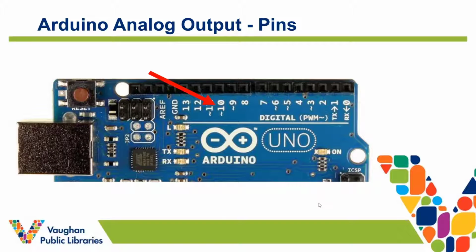If you remember Arduino Uno, we talked about that before, it has a couple of pins on the top side and a couple of pins on the bottom side. For example, analog input pins are on the bottom side. But on the top side, we use pin number 0 to 13, 14 pins only for digital purposes, for example, digital output or digital input. But we can use not all of them, only 6 of them, as an analog output.